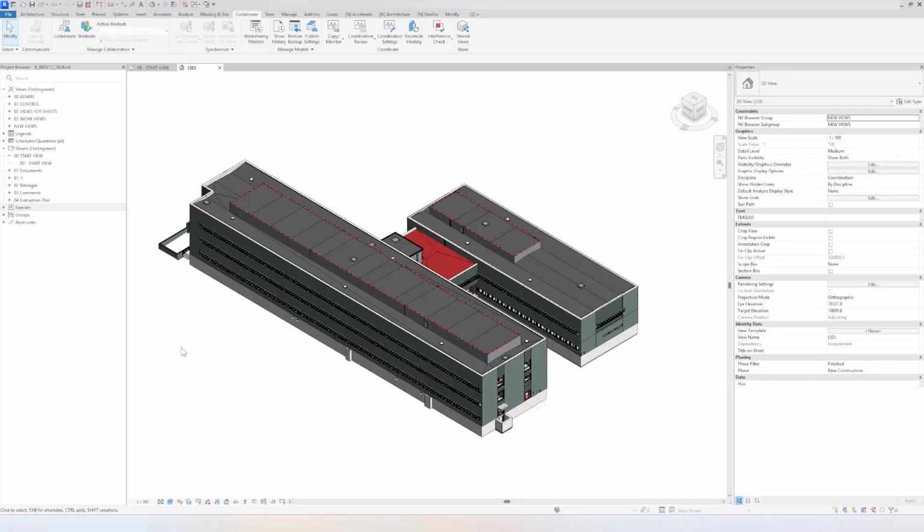We're going to go through how to create horizontal compartmentation using the Copy&Monitor feature in Revit. When we use the Copy&Monitor feature, we either use the architect model or the structural model, and this all depends on which project we're working with. It can either be the structural model, depending how they have done it, and sometimes it's going to be the architect model. It doesn't really matter, but in this case, we will use the architect model in this example today.